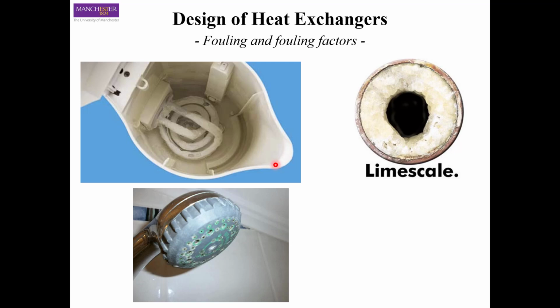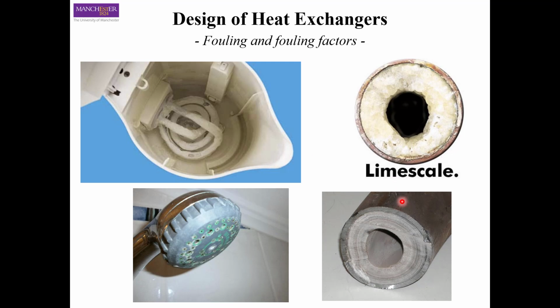But we can have also other situations, for example, when we have polymerization or the reaction of the components of the liquid inside the tube with the wall of the tube. Okay, so because of this reaction, we can have this form of fouling around the inner tube, but we can also have fouling outside the tube due to the fluid in the shell as well.